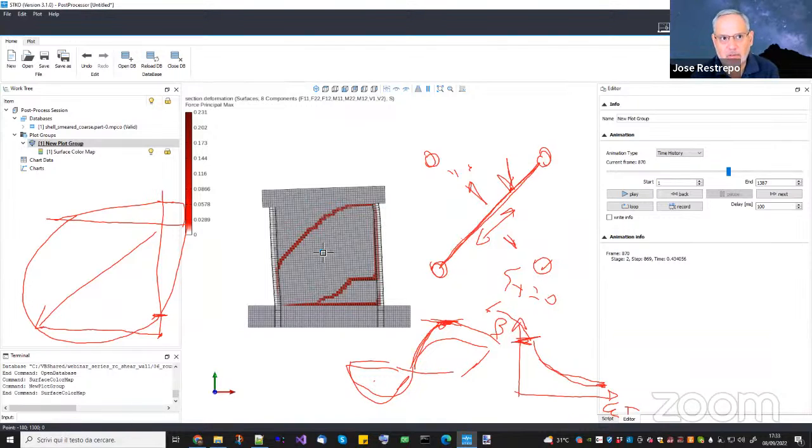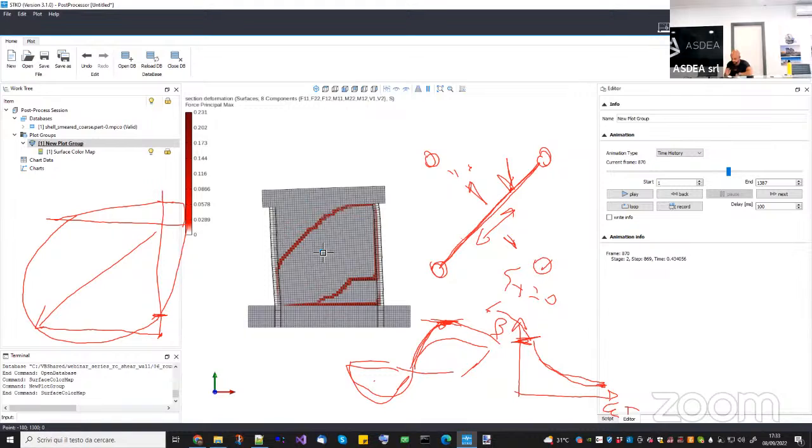You calculate if you're going to have a triaxial, no, biaxial, triaxial stress state like the boundary elements. You explicitly calculate the effect of the confinement on the 1D stress-strain relationship, and that enters. But that does not change during the analysis. It's so defined. For the user, exactly.